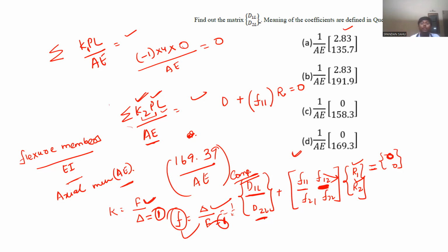Then you apply a unit load one at a time. If there are more, one at a time. You have to apply unit load one at a time, not both or all at a time. It is like an incremental process. You have to do it sequentially, not simultaneously. You have to do it sequentially.